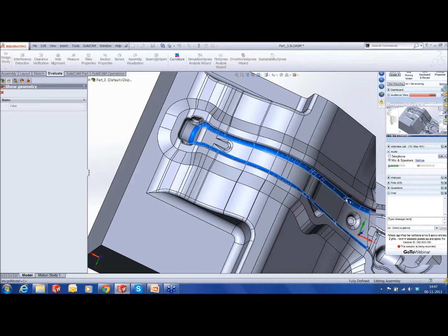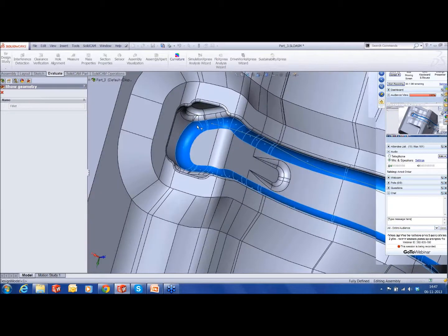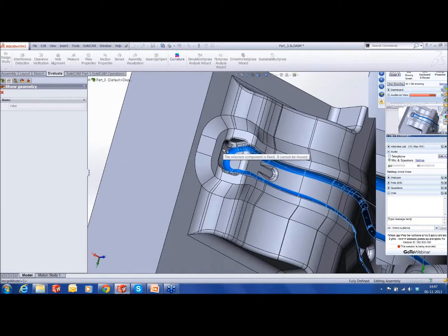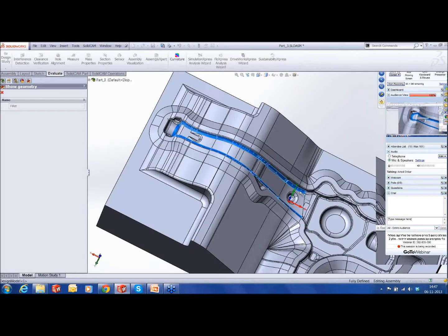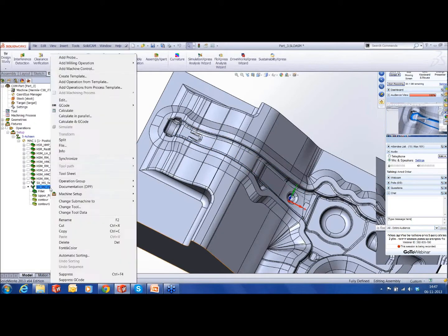What it does basically is it creates chatter on the surfaces where the tool tries to approach, where the L/D ratio goes up. In such places you will see chatter and vibration coming up, especially when you go into this region out here. It's really very difficult to cut this part without chatter or vibration. So what I've done is I'm going to use full 5-axis with full gouge control to cut only these fillets. So what do I have in my process?